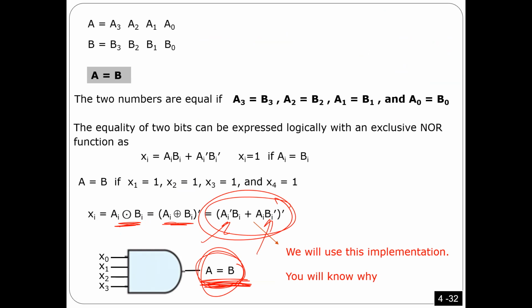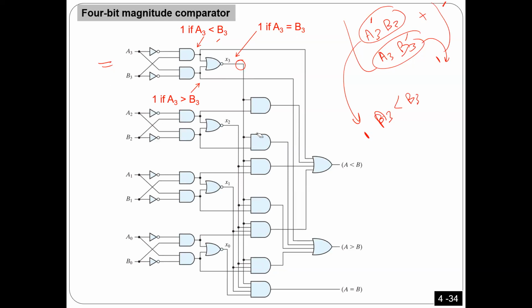So you can see here, if you look at only one circuit, this one is 1 when A is less than B, bit to bit. This one is 1 when A is greater. And then I put a NOR here so that, using these two magic terms, if I NOR them, this will be 1 if they are equal. You got what I'm saying? So now it became very simple. For every 2 digits, I have three important things: one for less, one for greater, one for equal, and then I'm going to use them here. Okay, so let's see how.